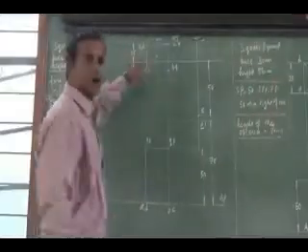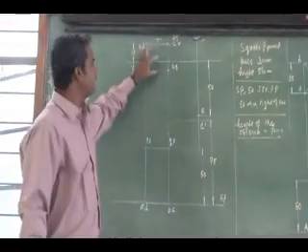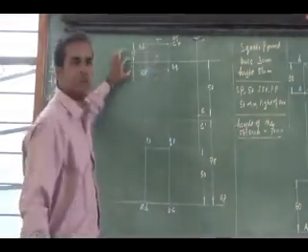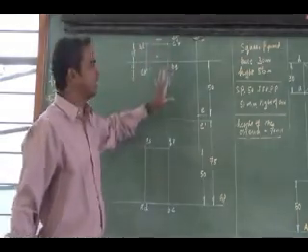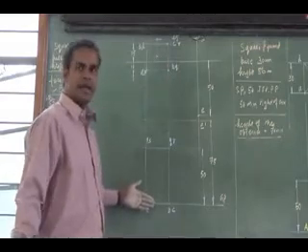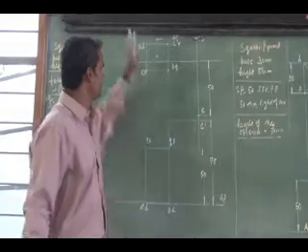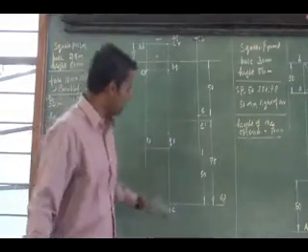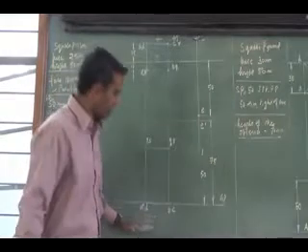Here, drawing the layout, it is kept vertically and the face is parallel and the face is 10 mm in front of the picture plane. You have to draw the top view as a square, right? Then the front view will be a rectangle for the height 50, straight away projected. Then you leave a gap for the ground plane.